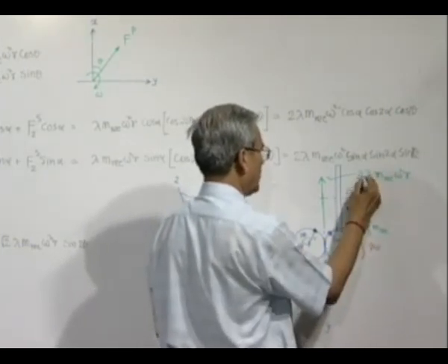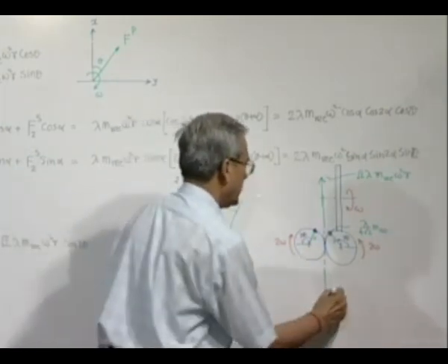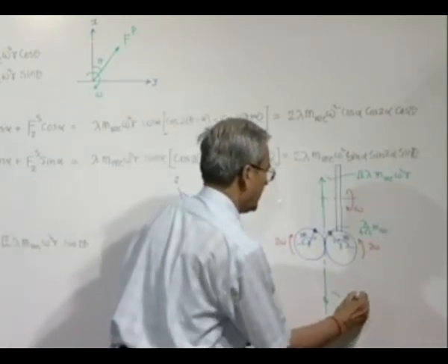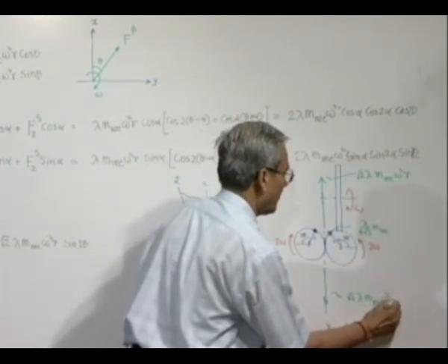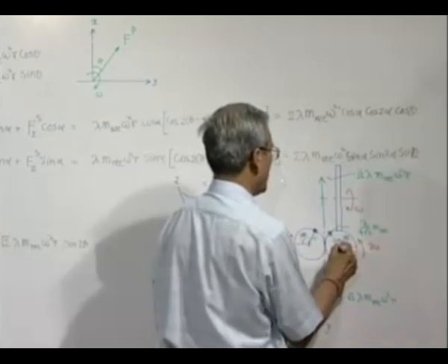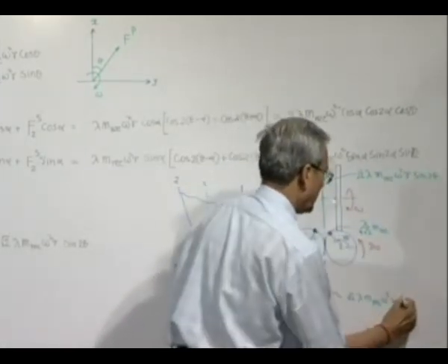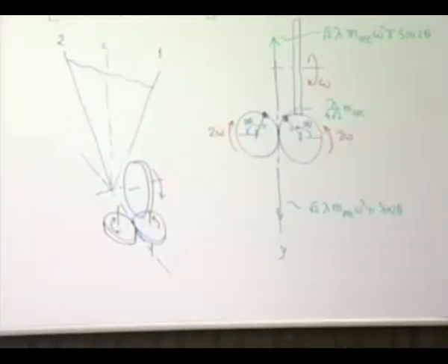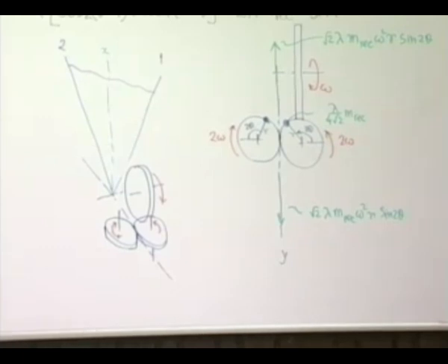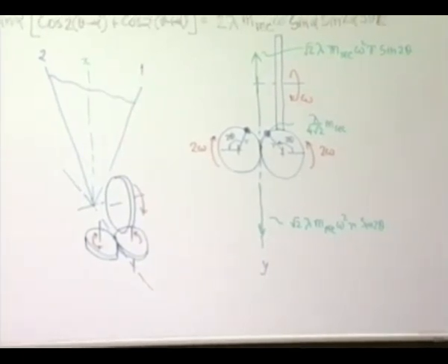So, here will be 1 2 and the original unbalance produced by the two engines is the same again. And here of course, this component will be sin 2 theta and we already know sin 2 theta. So thus, at every instant, the force developed in the engine can be balanced by the two centrifugal forces rotating in the opposite direction at every instant.